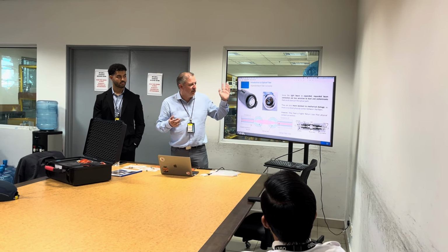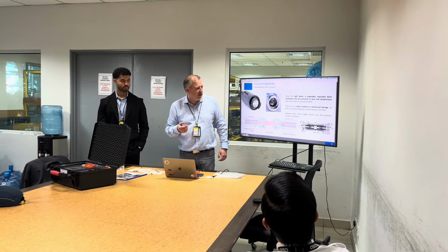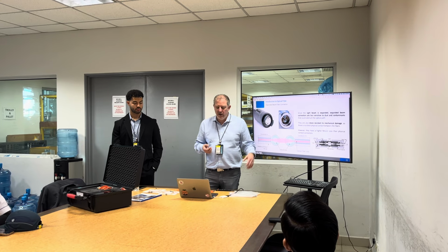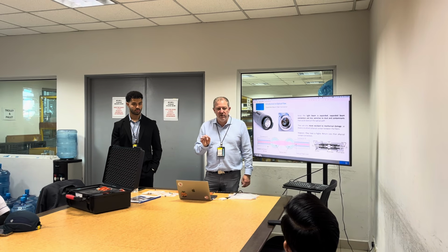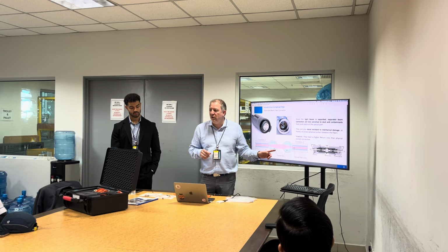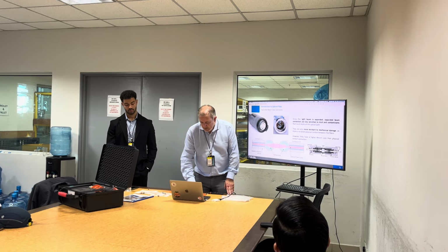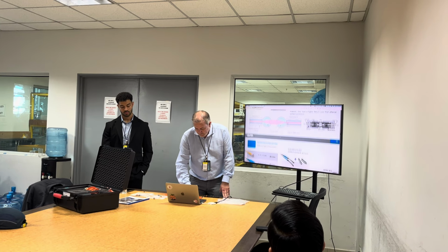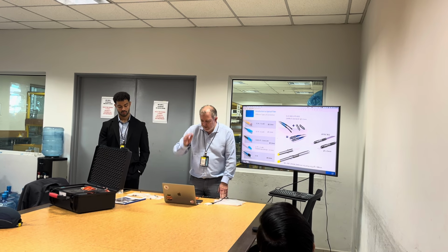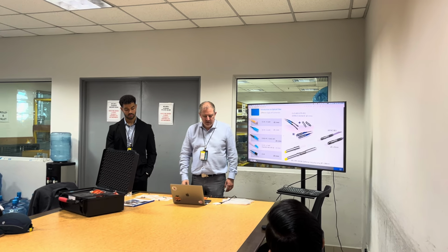Just in case in your life you encounter this kind of expanded beam connector, it's a little bit more sophisticated, and they usually work only for one specific wavelength, because you have a specific surface treatment to avoid any reflection on the lens. So these are different connectors again that you can find.